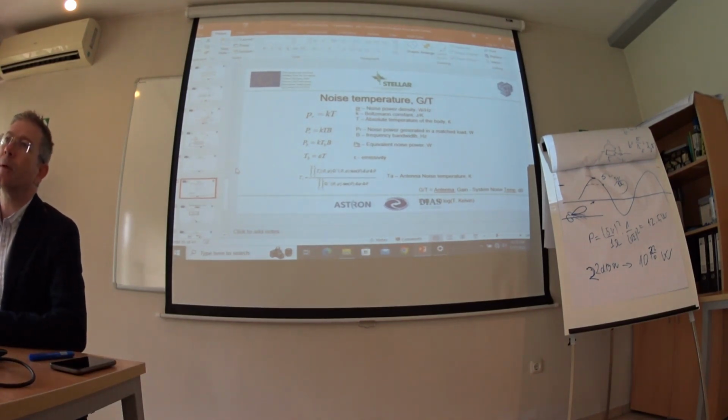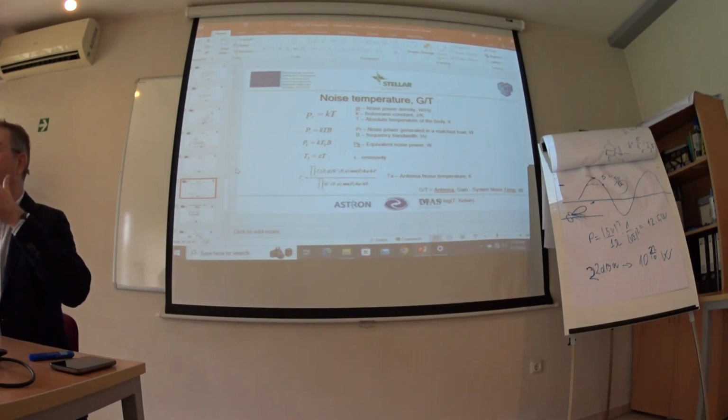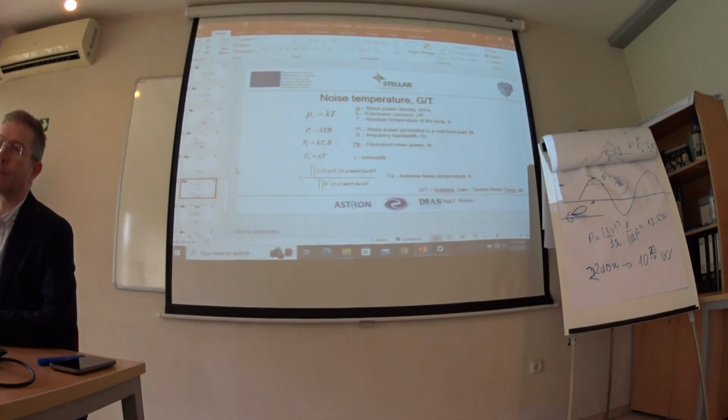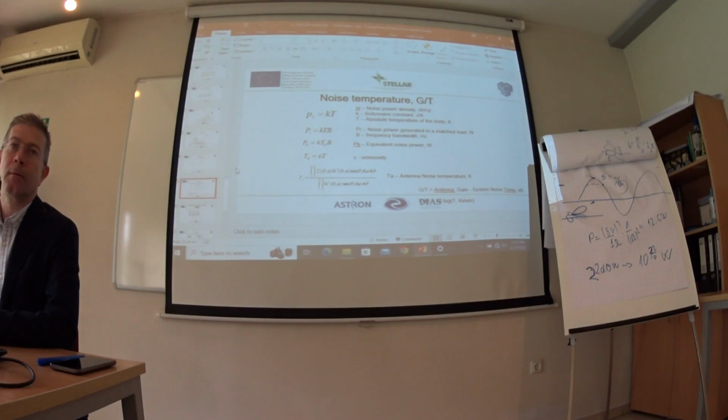Good. For a home satellite antenna, a typical G over T value is about 13 decibels. About 13. For a radio astronomy antenna, a large antenna reflector, maybe 25, 30, 40, 300. 300 could be. If you want to communicate with Mars, Mars is really far away. We need a large antenna with a cryogenic amplifier.